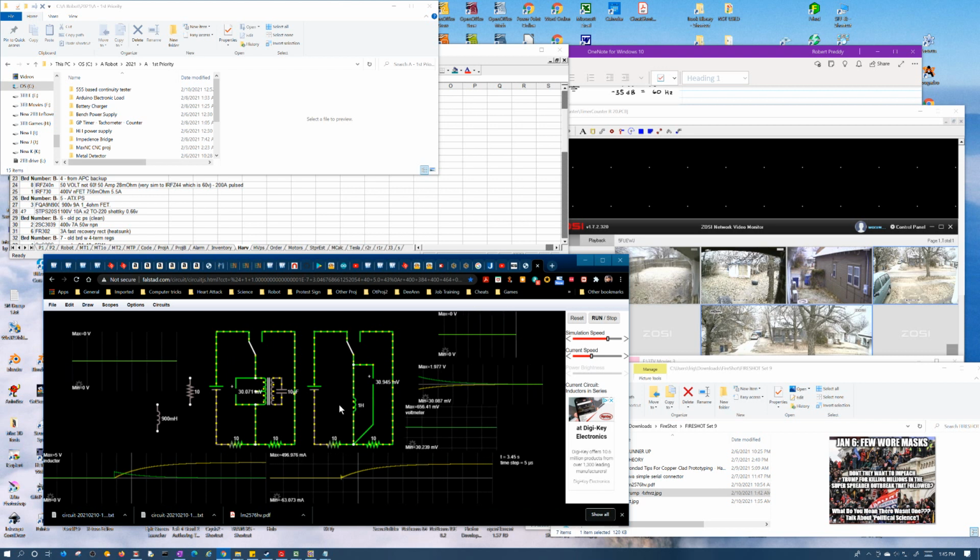Because remember, once you get one of these inductors fully charged up, it has maximum current through it. It has 0 voltage across it, but it's got maximum energy stored in the field. So then when you dump it, by switching it, it generates an electric field substantial enough to try to maintain that current. But it flips its polarity when it does it. So anyway, let's give it a whack.